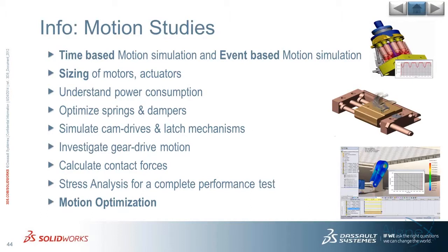And then also we can take any snapshot in time of our motion study and actually do a stress analysis at that snapshot in time, a linear static analysis with the external forces that are acting on a single body.